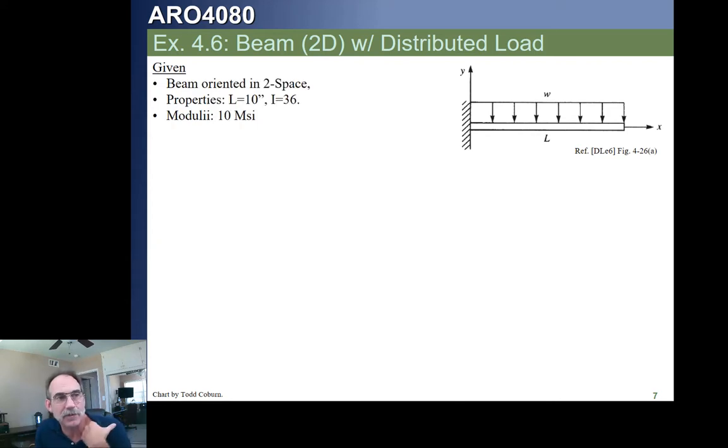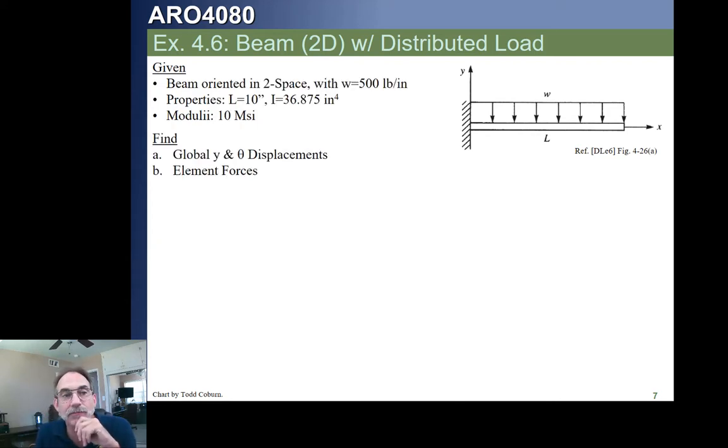Let's say I have a cantilever beam with a distributed load. You'll notice there are no external loads except for that distributed load. In order to account for that, since we mostly are looking for information at the right end and at the left end, we can actually use a single beam element to solve for this. However, we're going to need to apply our distributed load, since that is applying to parts of the beam that are not at the nodes. Okay, so we're going to use our new procedure. So here's what we're going to do.